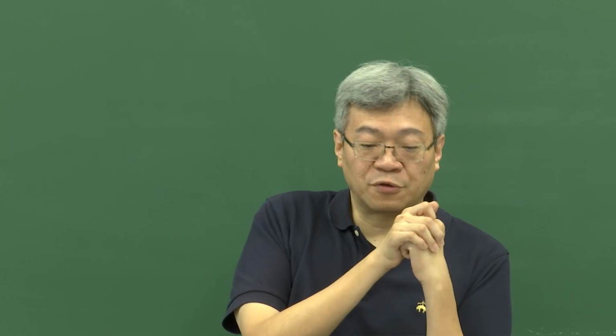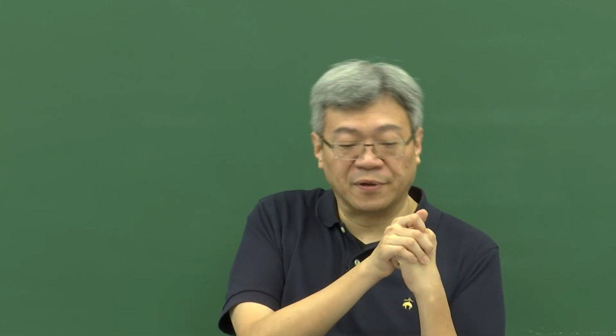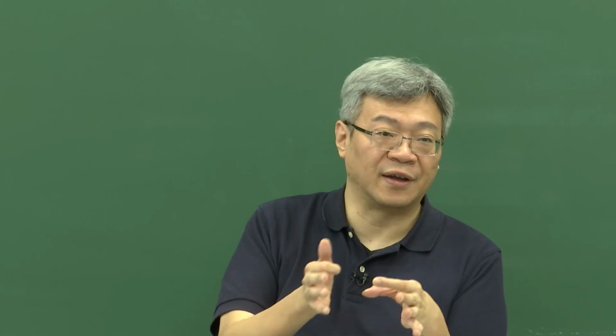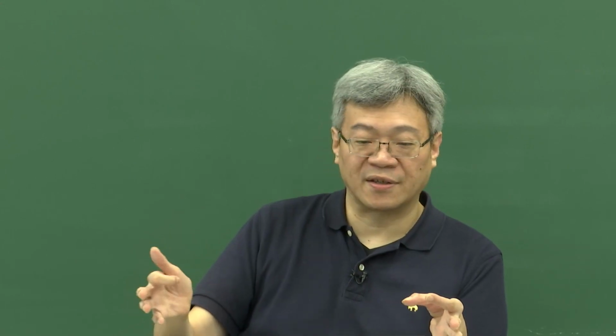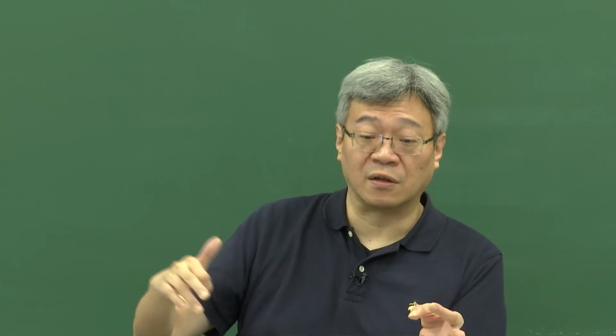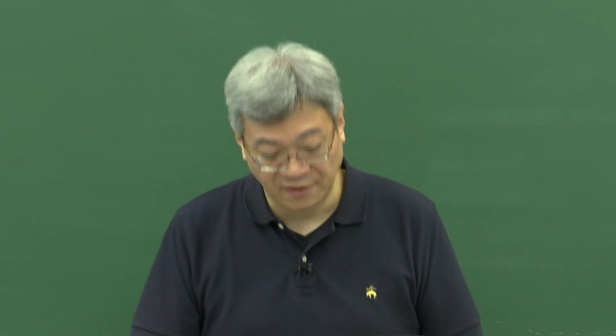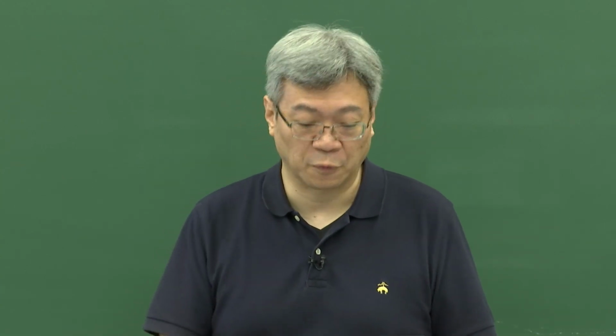But when the strain is high, like 2%, for example, you are going to pick up certain nonlinear elasticity, right? Because if the strain is not small enough, you are expecting to see those higher order terms. So if you include those terms, you are going to see an asymmetric contribution, which means when you compress or stretch your solid, you are going to pick up a slightly asymmetric response.